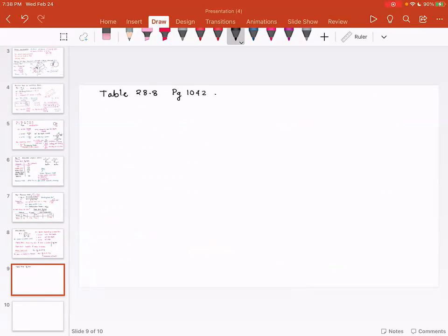If you look at this table, it talks about the material, the Brinell hardness number, and the value of sigma E. For materials such as cast iron, the BHN is typically about 160, which is moderate to low, and sigma E is 84.